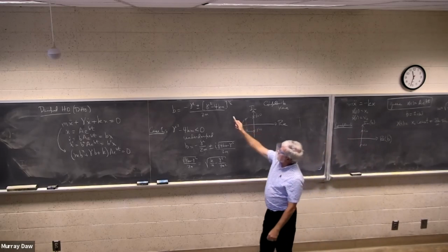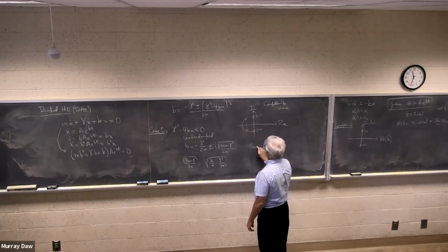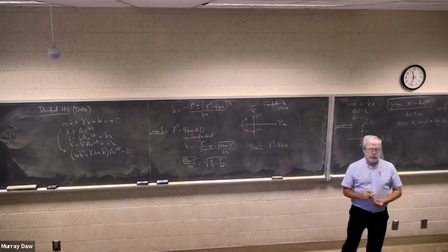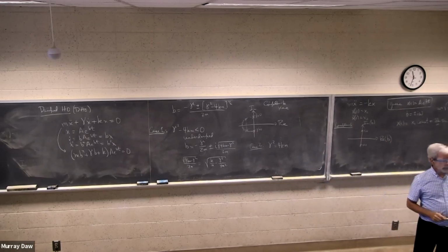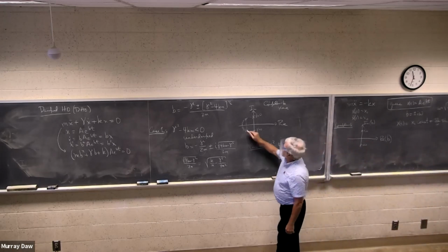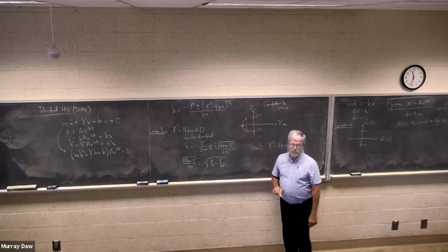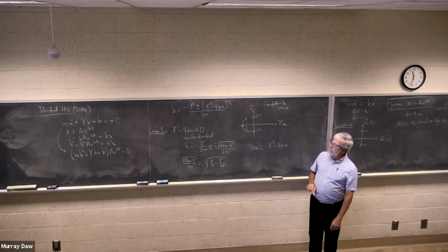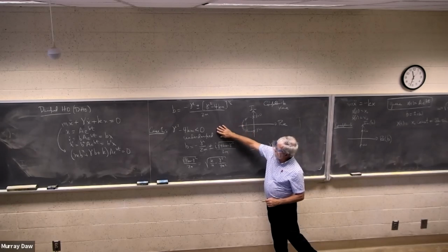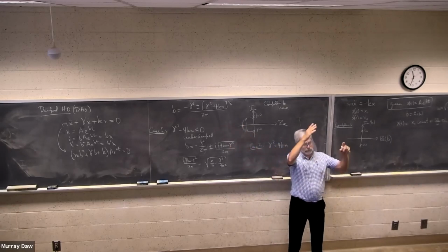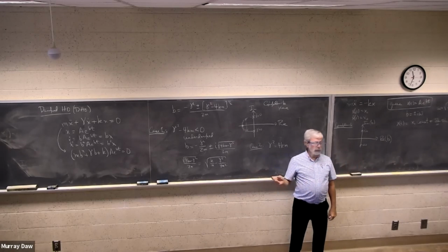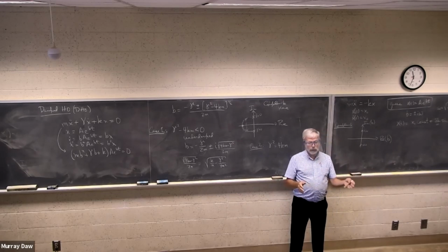Okay, now if the discriminant is equal to 0, that would be case 2. The damping is right at critical value. Gamma is equal to root 4 km. Imaginary part's gone away. So there's no oscillation taking place anymore, right? Before, B had a complex value, so it's got damped oscillation. Both the cosine and the sine parts are damped. That corresponds to the mass on the spring just slowly losing its energy.